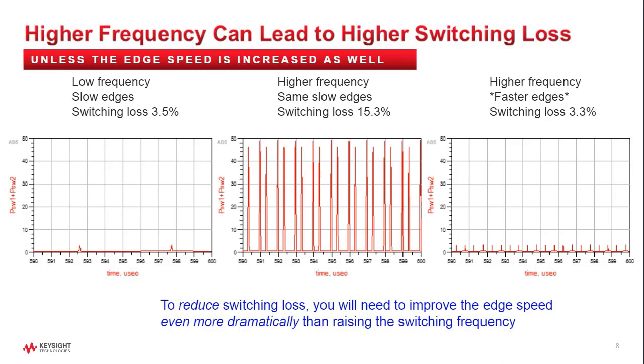if any of you are RF amplifier people, you know the efficiency is a function of how I can get these transistors to switch so that I've got the conduction states exactly the way I want them. So this is where some of the problems have come up, where people are using faster edges, and with the faster edges, that L di/dt is creating voltage spikes because the parasitic inductances haven't been accounted for.